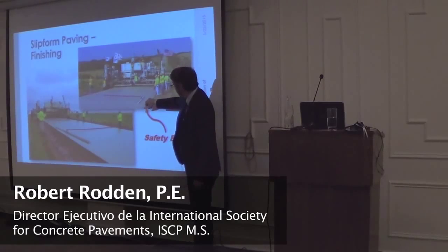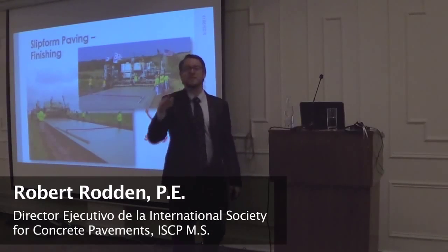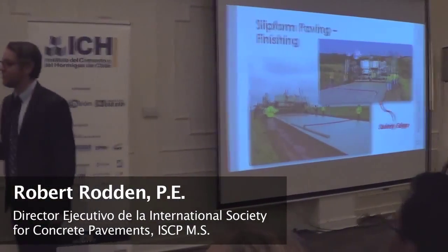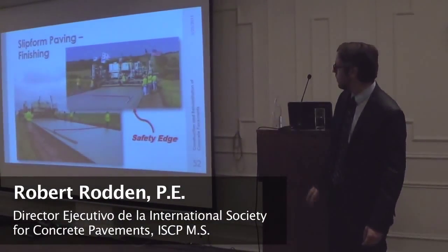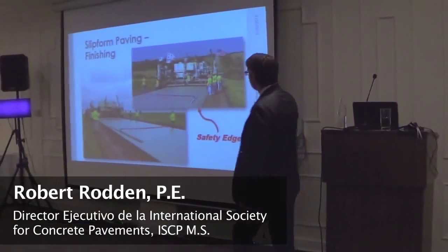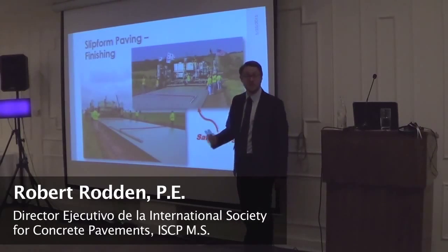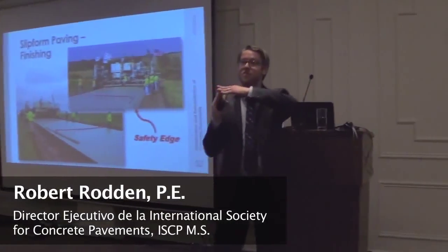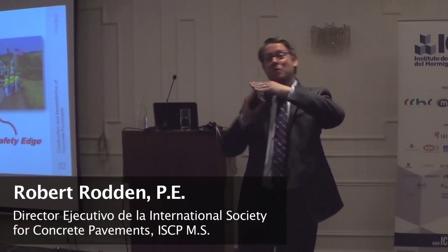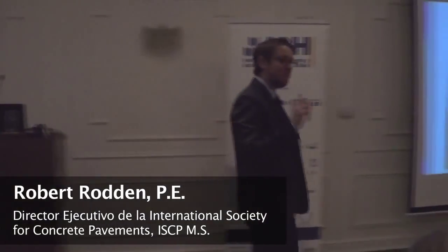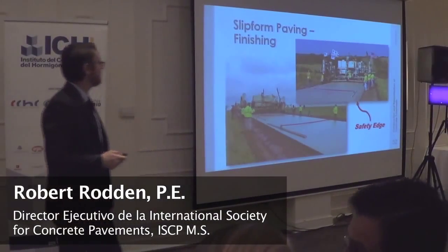So we've devised this safety edge, which is just a fillet. So as the shoulder starts to move away from the concrete slab itself, that problem is less, because they have this nice transition back onto the slab. So we're seeing that applied. Our Federal Highway Administration was a big pusher in this on lower volume roadways. We're doing it on asphalt and concrete pavements. It's no harder for them to build this into the pavement than it is to make the edge perfectly straight. In fact, if that's the outside edge, having this helps with the slump. So it's minor detail, huge safety impacts.